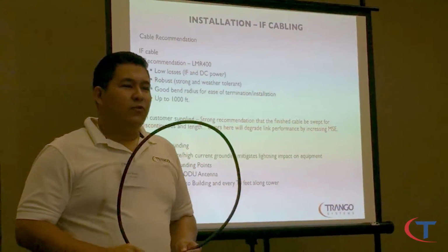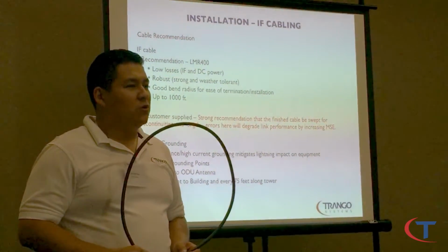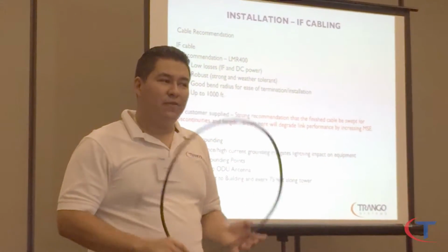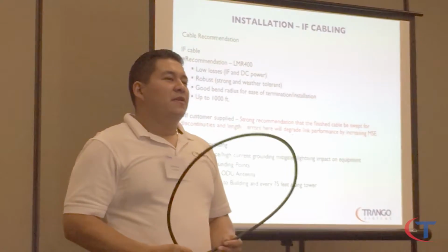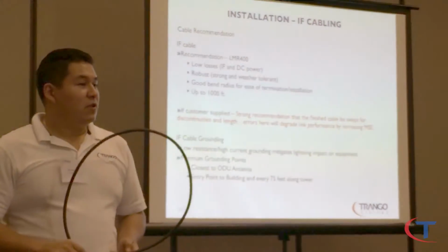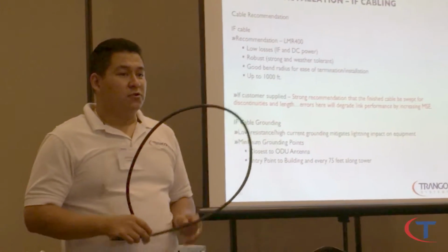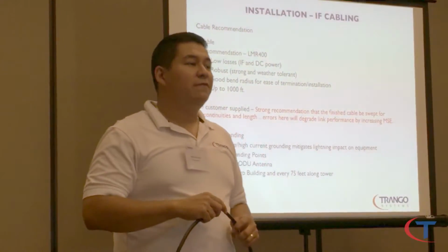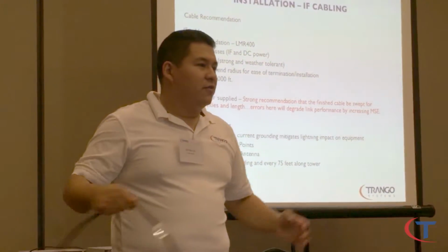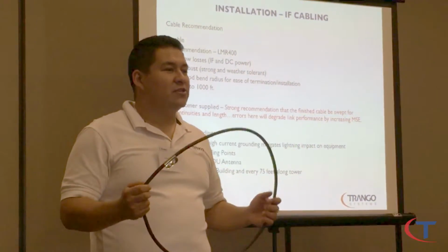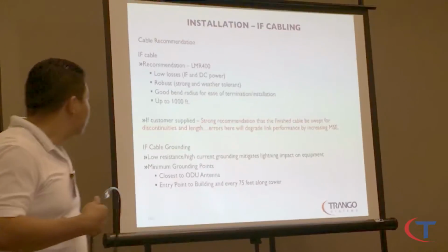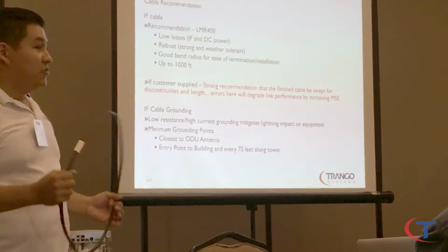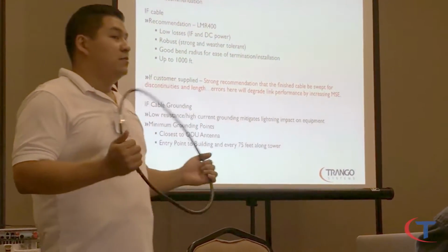On this note, the return loss of the radio depends on the power as well. On cable runs with LMR 400 from 100 to 150 feet, you have to be really careful how you terminate your end connectors. The return loss at 150 feet is really finicky. If you go longer, you actually get easier results with ease of installation. If you build the cable yourselves, make sure you sweep the cable and check the frequencies on the cable.